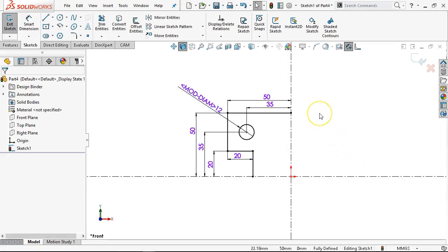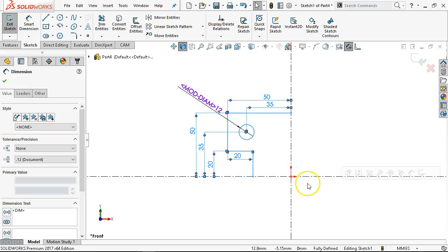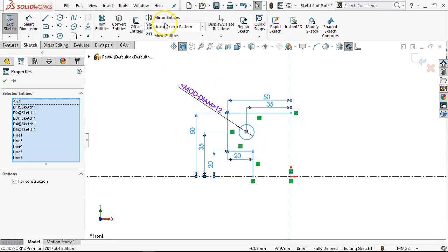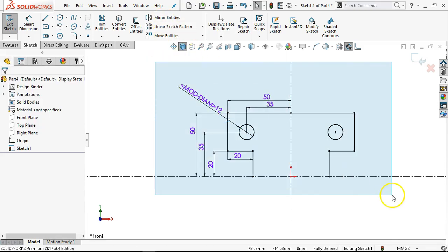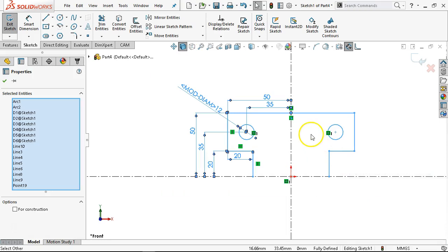Okay, so since we have the two center lines, this time I'm going to go from left to right, pick all of my geometry, and then control select the one that I want. All right, so that goes into mirror. If I don't pre-select, all right, so I haven't grabbed a center line. Going from left to right is everything inside the window.